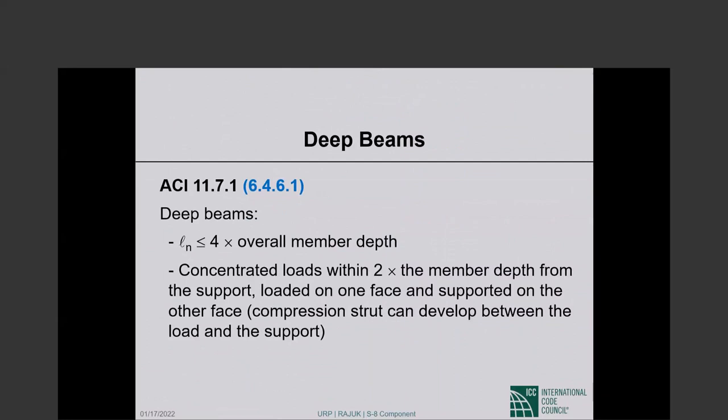So I started from strength of materials, as you saw, trying to make the point that we are designing for diagonal tension, and then the concrete contribution to shear strength and the contribution of the shear reinforcement to shear strength. The concrete contribution has multiple parts: the shear in the compression concrete, the dowel shear, the aggregate interlock shear, and all of that we kind of lump together in typical applications.